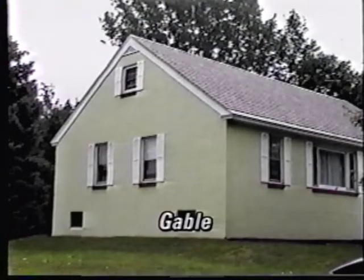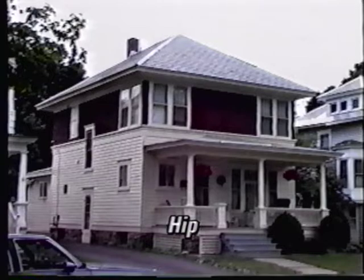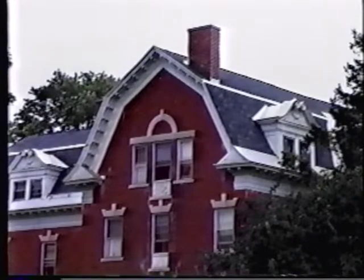The gable roof is the most common. It's comprised of 2 sides that slope up from 2 bearing walls and meet at a ridge pole or ridge area. Hip roofs have 4 independent sides that slope up from 4 bearing walls and meet at 1 ridge. Gambrel and mansard roofs each have 2 slopes per side, with the lower slope being steeper than the upper one. The difference between the two is that the mansard roof rises from 4 sides, while the gambrel rises from 2.